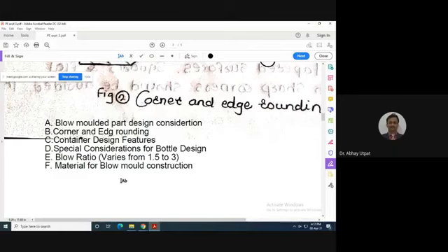Whatever mold you have prepared must have the strength to withstand the heating and cooling cycle of the plastic component. So the first material is aluminum alloy. Usually this is a high grade aluminum alloy, maybe the material used in aircraft, and it also includes zinc, magnesium, copper, chromium as alloying elements. It has good thermal conductivity, good machinability, and as it is light in weight, it carries very high benefit.